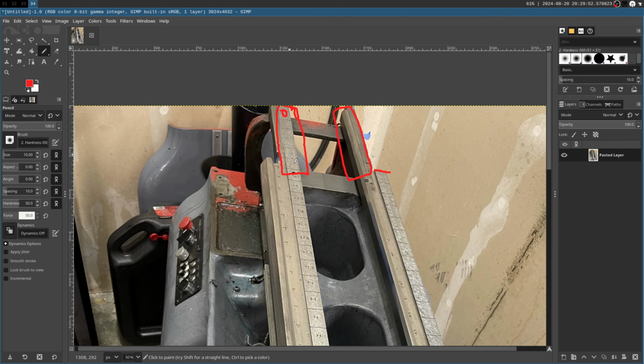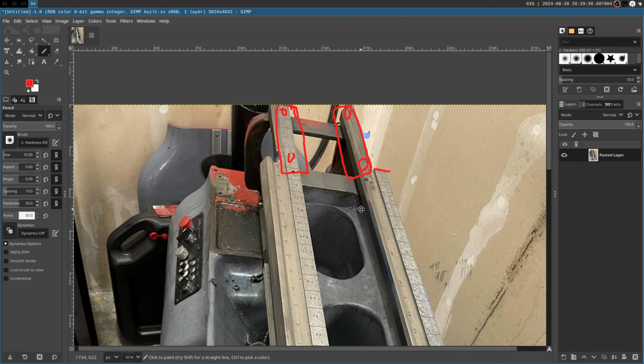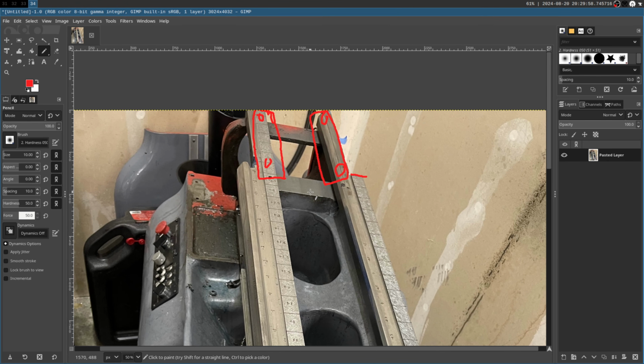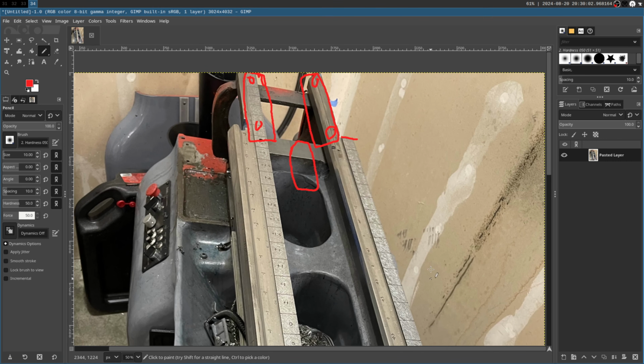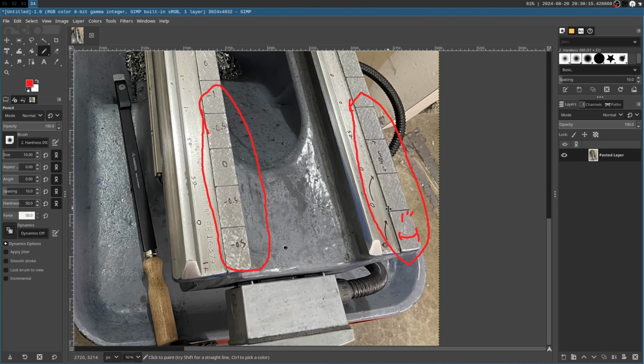And these are the 4 bearing points of the headstock, which basically determines where the spindle rides in its axis with respect to the lathe. So these points will be extremely critically scraped in, but we're not even thinking about the head, just giving some reference of where everything is on the lathe.